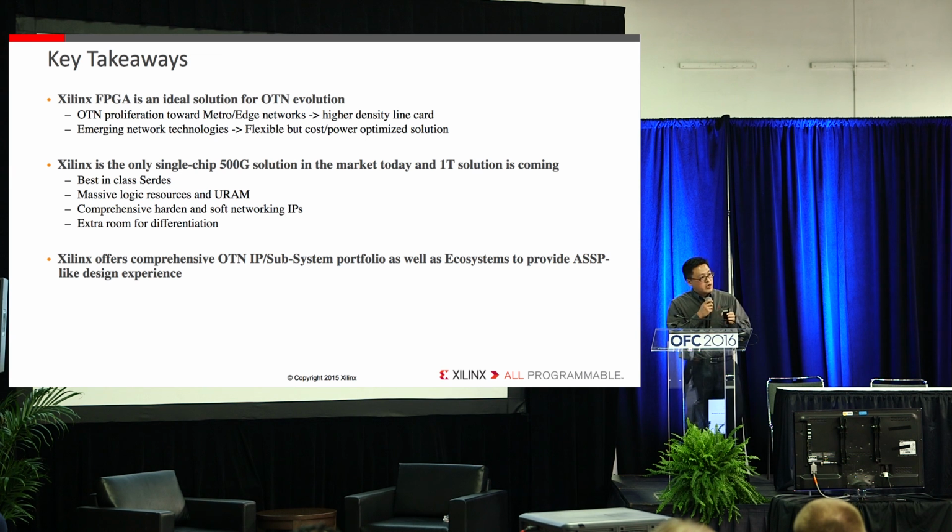And today we have field-proven 28 gig I/Os, backplane capable, and now with the PAM4 demo that we have today, that is again re-anchoring how much focus Xilinx has put into I/O technologies. I would also claim that the PAM4 I/O that we are demoing today is also backplane capable, and we have a 40 dB channel in our demo, and I would encourage you to take a look at that.